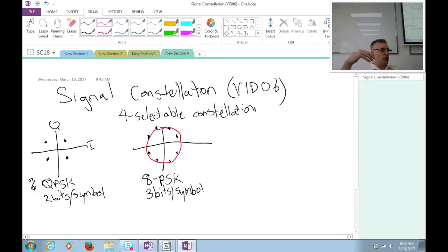This is the thing that draws probably the most power, the single thing that draws the most power on a real geostationary Earth orbit communication satellite, that power amplifier. So in order to make it efficient, you've got to tolerate some nonlinearities. Well, using QAM is not a good method for transmitting through a nonlinear power amplifier because, as we said earlier, it distorts different parts of the QAM spectrum differently.